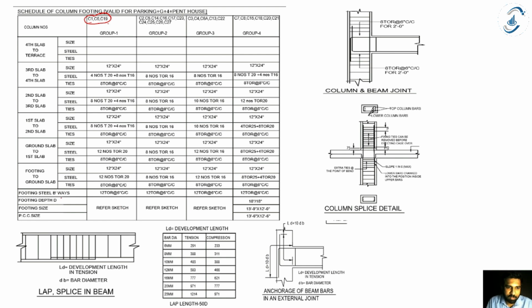So we have already studied this part. Your PCC size is also given. Now what is a PCC? It is a firm base that is created in the excavation pit over which your foundation is laid. So we have the PCC size, we have the footing size, we have the depth of my foundation, and we have the footing details. We have just studied this a few moments back.